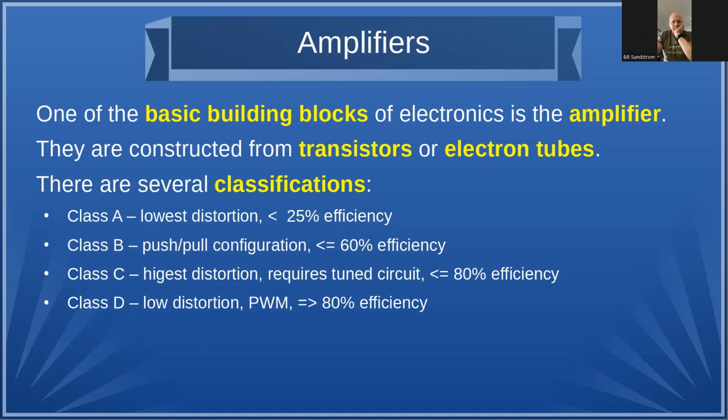And then you've got essentially a digital class D, which uses a pulse width modulation technique where it outputs a variable width pulse that's proportional to the amplitude of the input signal. And it makes it very easy to then filter that and recover the signal. But it allows you to use almost, in essence, switching transistors. So you get very high efficiency. They're either on or off. There's no in-between state.